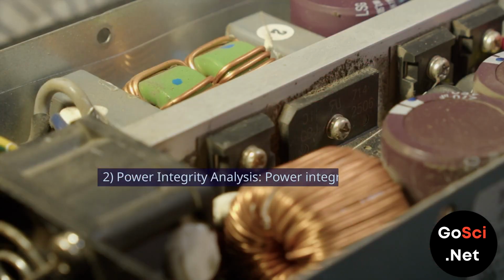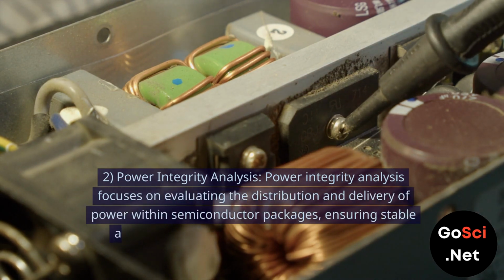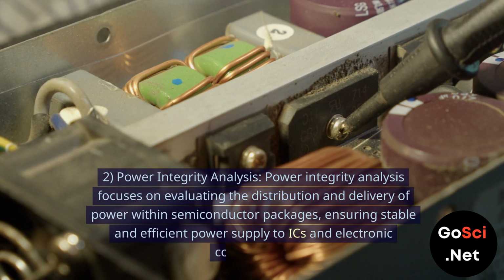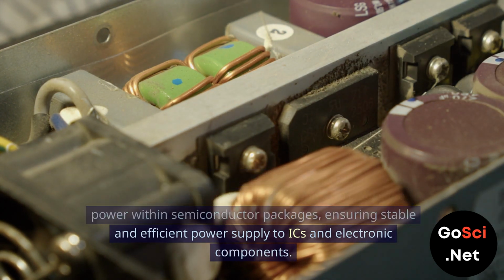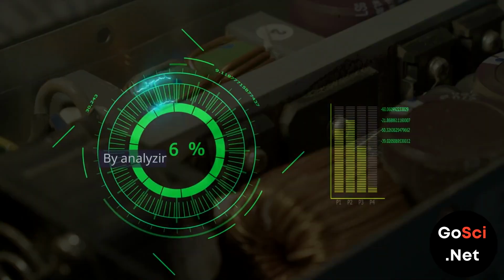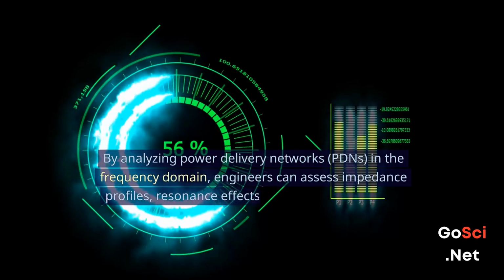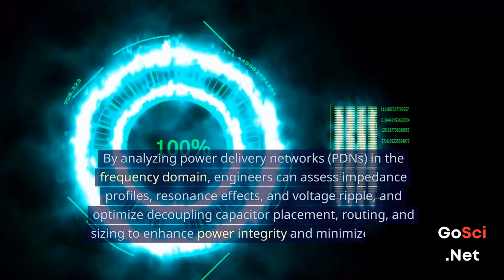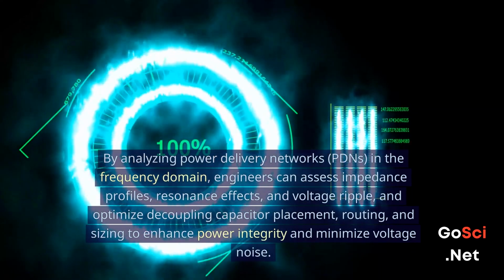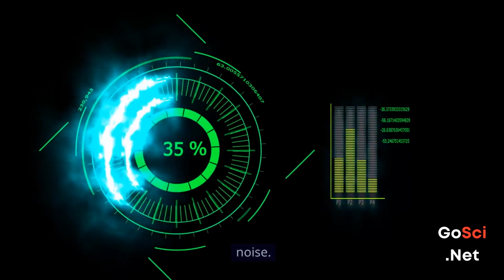2. Power integrity analysis. Power integrity analysis focuses on evaluating the distribution and delivery of power within semiconductor packages, ensuring stable and efficient power supply to ICs and electronic components. By analyzing power delivery networks (PDNs) in the frequency domain, engineers can assess impedance profiles, resonance effects, and voltage ripple, and optimize decoupling capacitor placement, routing, and sizing to enhance power integrity and minimize voltage noise.